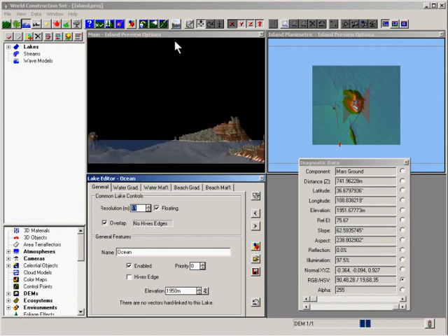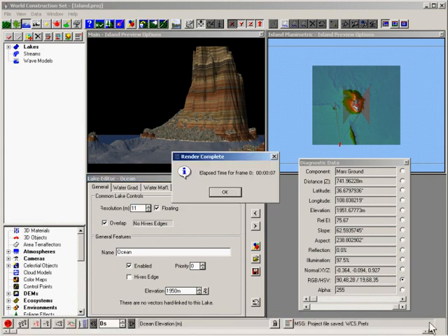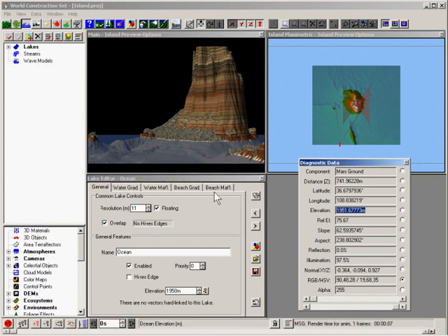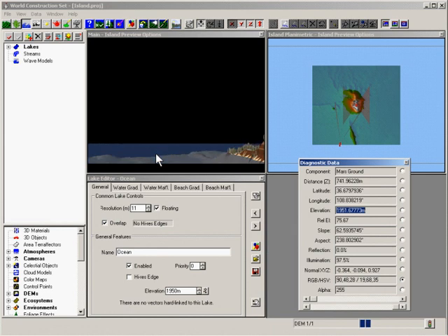I'm going to use the Escape key to stop the render. You can also use the Abort Operations stoplight button at the right end of the animation toolbar. I'm doing this to show you the new transparent water feature in WCS 6. I stopped the render because most of the transparency will be lost in the reflections pass. Start the render again, and let's see our scene so far.